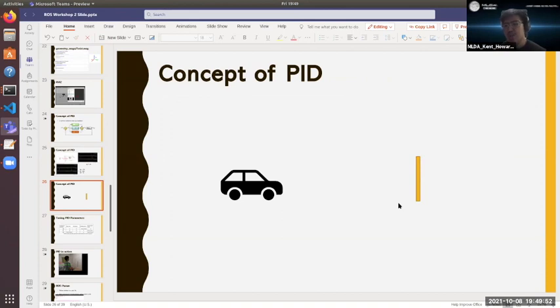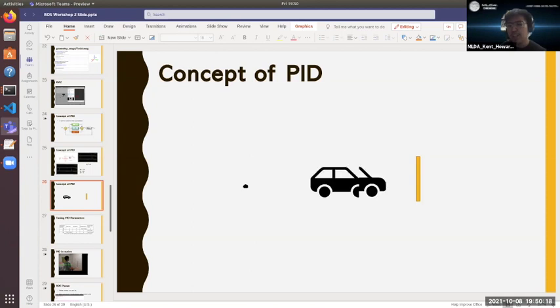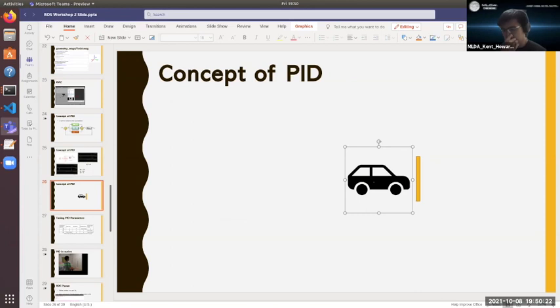So usually there's one method that I'm aware of, I think the name is Twiddle or something. Essentially, they use some sort of machine learning to iterate through every possible value. So you start with a value of KP, increase the KP, and see if it gives a better response. For example, if your parameter for your response is how quick you reach the goal, for example.